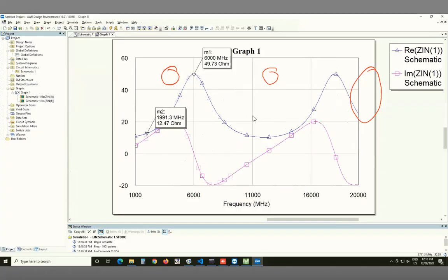Now it's exactly as we said, at 18 gigahertz here it's back to lambda by 4. Okay, so is this part clear? A transformer at one frequency could be a different transformer at a different frequency. So one has to keep that in mind.